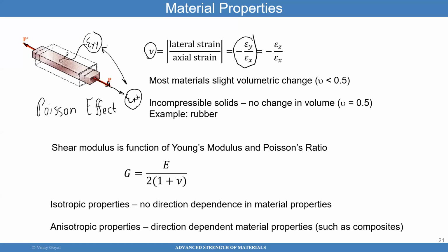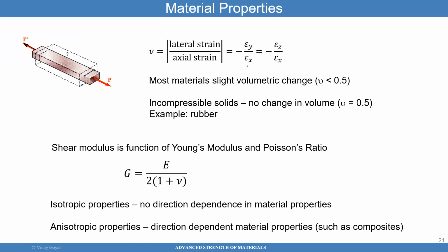Most materials have a Poisson ratio closer to 0.3. But a rubber material is going to have a Poisson ratio of 0.5. And you see that a lot. If you take a piece of rubber and pull it, you're going to see the cross-section quickly decrease in size compared to aluminum. So clearly, when you stretch in one direction, it contracts in the other. And there's a negative sign because it makes sense: if I apply a positive load in one direction, it stretches, and it contracts in the other.